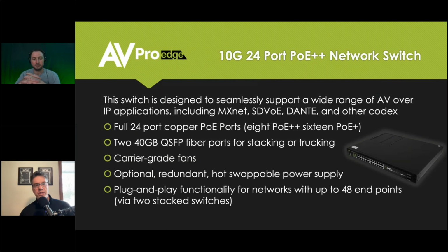All right, so this switch is designed to seamlessly support a wide range of AV over IP: 24 ports copper PoE, 8 PoE++, 16 PoE+, 2 40 gigabit QSFP fiber ports. We have carrier grade fans, an option for redundant hot swappable power supply. And of course, it's plug and play.